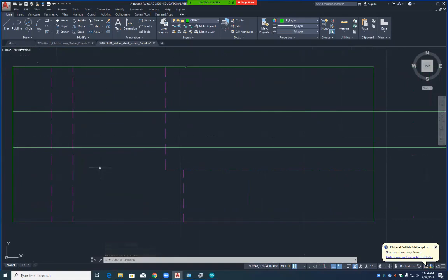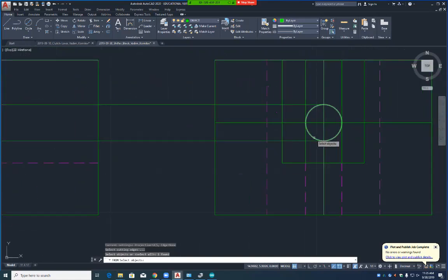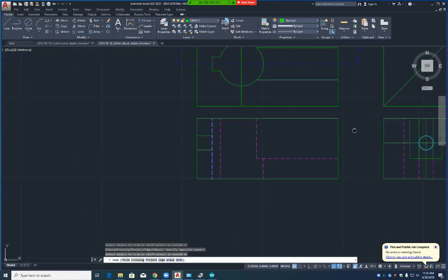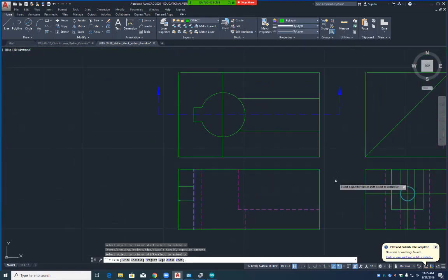Okay. So now, what happens to all these hidden lines now? Now remember, we're removing this all right here, aren't we? Okay. They become object lines. They all become object lines. What happens to these 2 lines right here? They go away. Why? Because you don't see those.